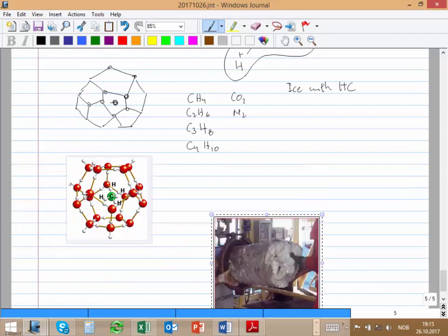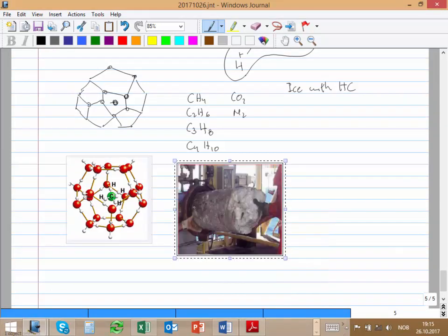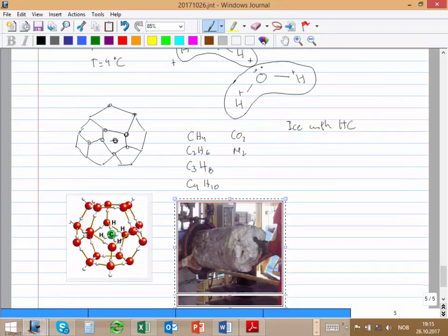You see, like you say, no problem. Here in Mozambique, if we have a pipe producing from the field, it's always 20 inches minimum, maybe 16, so we don't have this hydrate problem. But you will have it in these fields that are in the subsea. You are 1,500 meters down, the temperature might be 4 or 5, and then you have to worry about hydrates. You have to worry about having a good insulation.